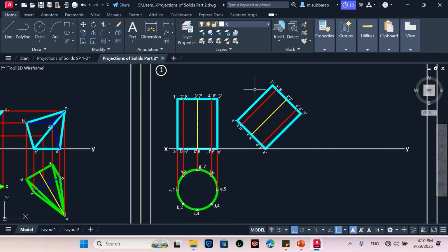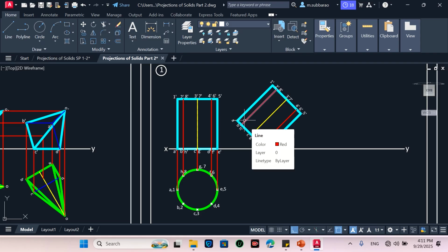So now I got view 1, view 2, view 3. This is the front view, and now I need to get view 4 by projecting each point. I also gave an example that if I join the leftmost corner with the rightmost corner, then above the joining line all the edges will be visible. So in the top view, all the edges of the top base will be visible, and in the bottom base only some of the things will be visible.